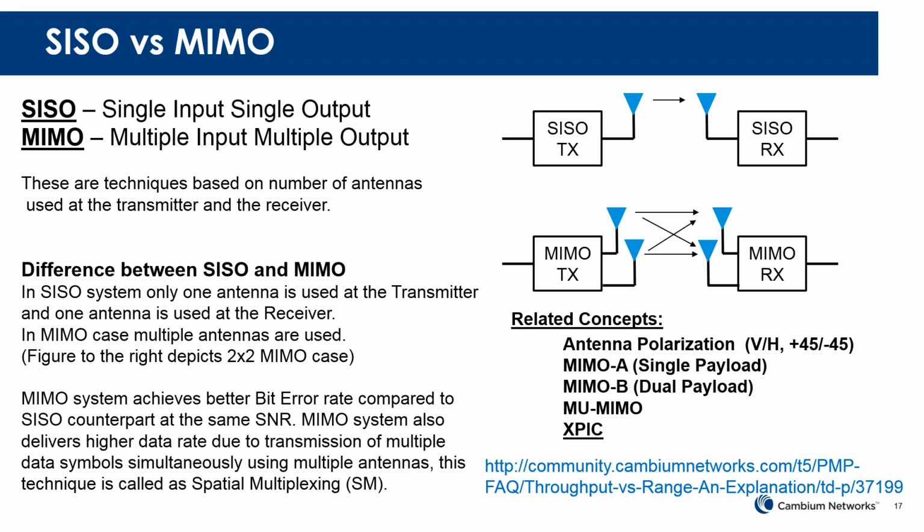I believe it's referencing cross-polarization interference cancellation. It's a way of using a single carrier frequency and doubling the capacity by almost doing a MIMO type of thing, using it twice, two transmitters, two receivers, and making sure that when one of the transmitters is talking, it is able to be canceled out of the opposing receiver at the other end. So basically you're transmitting two different sets of information, and the receivers are able to cancel out the unwanted transmitter's information because they know what you were sending, and it's doing this XPIC magic under the hood.